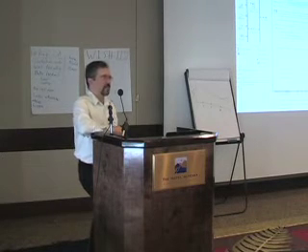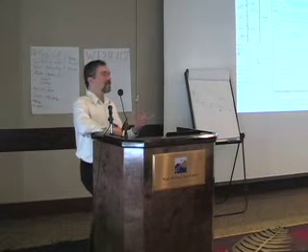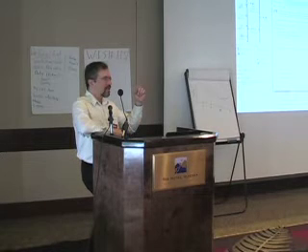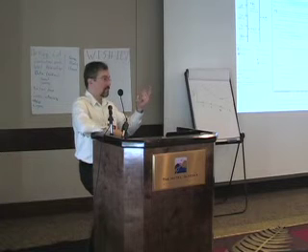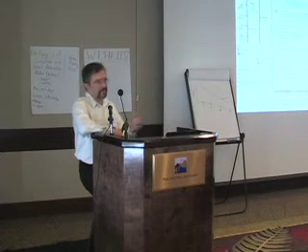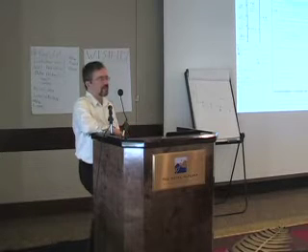Right. So it's important also to recognize that Homer is going to underestimate the actual throughput in the battery because it's not looking at power that's going in and out of the battery within a time step. That's a pretty important point. So I'm trying to be honest about what Homer doesn't do as well.